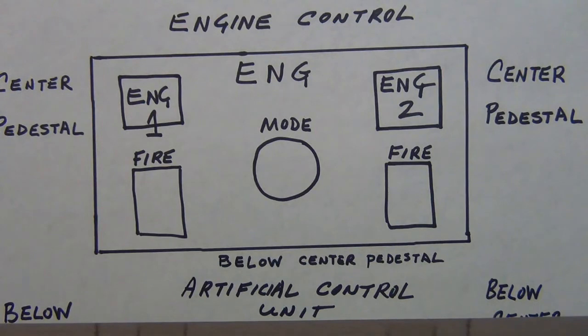So let's just say that the engine master switch, or manual start push button, is not selected. Let's just say it's not in the on position. Within 30 seconds, the pack valves are going to automatically open. Okay, and why is that? Why are they going to automatically open if we don't have a selection of on? Well, it's doing that to prevent unnecessary pack valve cycles.